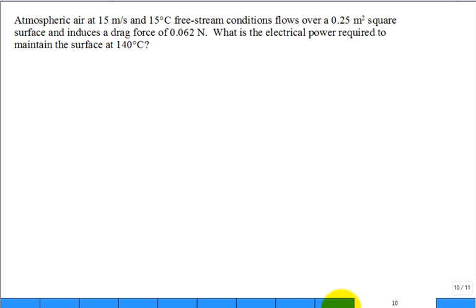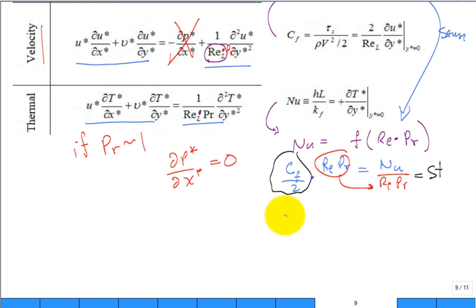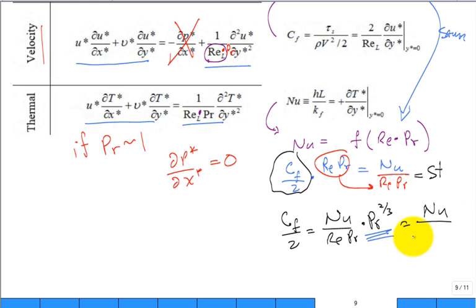Now, Colburn did a modification to this, and everybody uses the modified Reynolds analogy. He said, because we're trying to fit this to experimental data, it's really the Nusselt over the Reynolds Prandtl and just Prandtl to the 2/3. And you'll find the vast majority of literature put that Prandtl to the 2/3 in. So that you could even simplify it a little bit, Reynolds Prandtl to the 1/3.